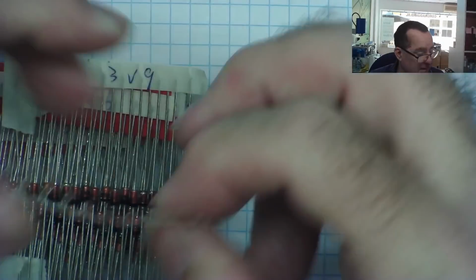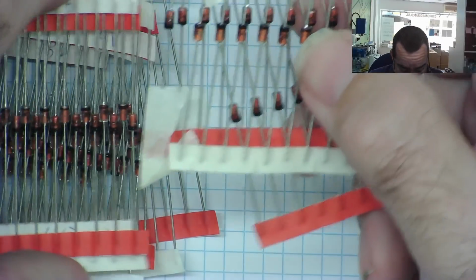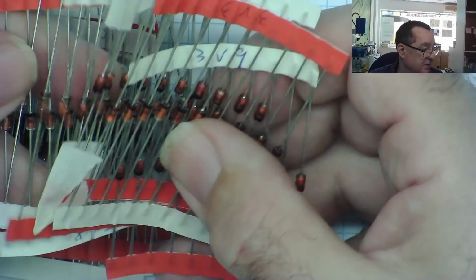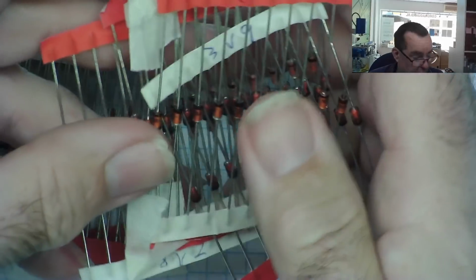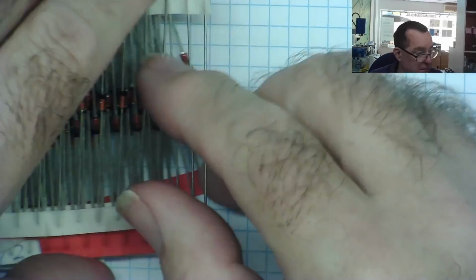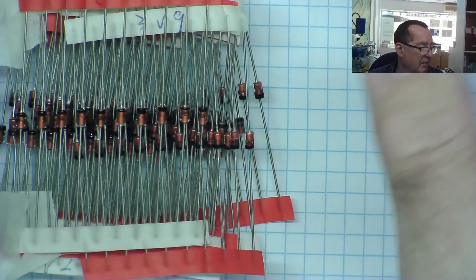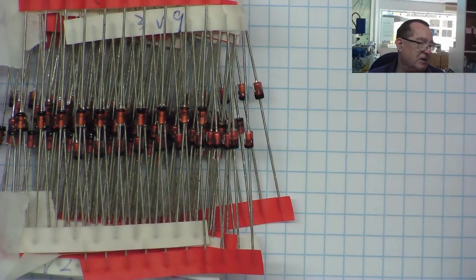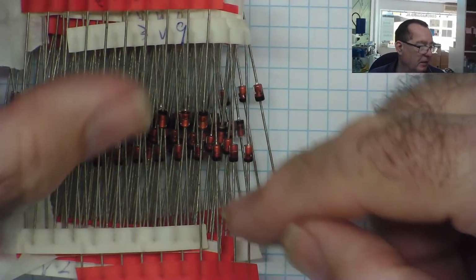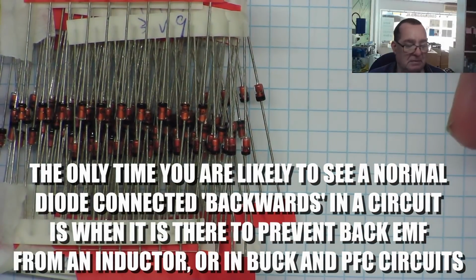You can see, looking at a Zener diode, they look much like a rectifier diode. You normally can't tell whether a Zener is a Zener or whether it's just a diode by looking at the device. It may have a part number on at one end, or it might be marked with a voltage. You can often tell if a diode is a Zener diode in two ways. One is the position in circuit. If effectively the cathode, the stripe, is towards the positive, it's most likely a Zener diode.